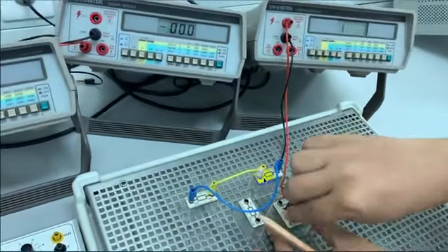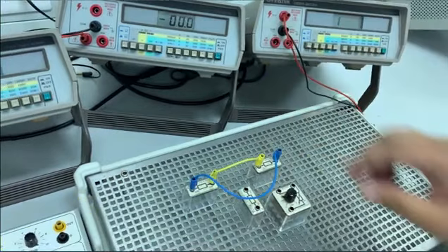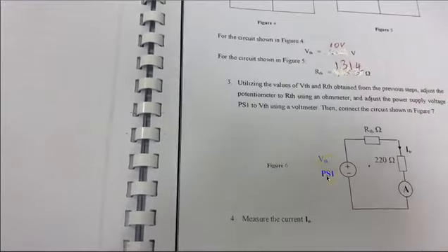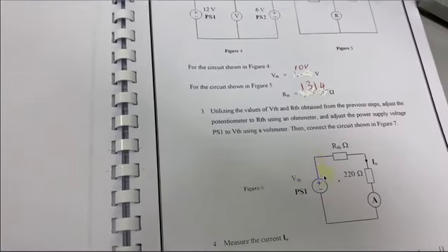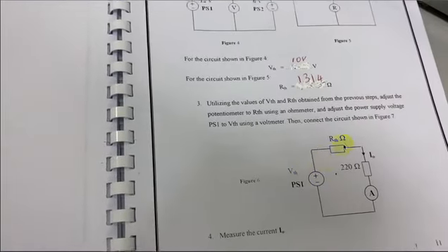Okay, Thevenin theorem. What is Thevenin theorem? We find total voltage as 10 volt and total resistance as 131.4. So now by using the potentiometer I have set the resistance value of 131, and now I will make the voltage how much? 10 volt. Now we can vary the voltage. So the voltage here with Thevenin is how much? 10 volt. We will connect the voltmeter and we can set the value.